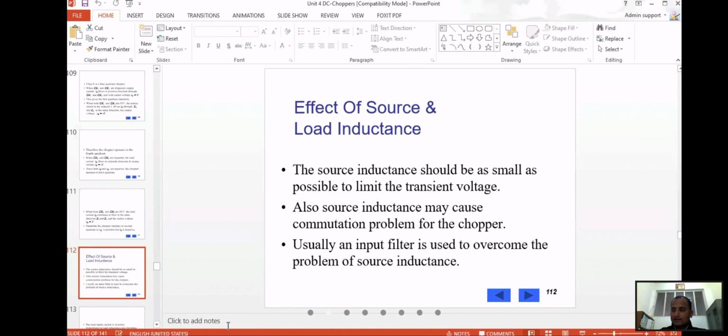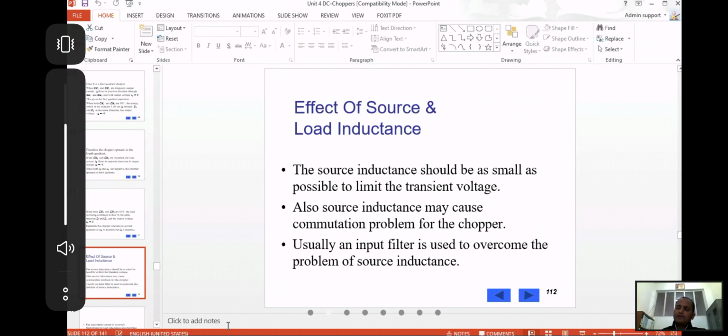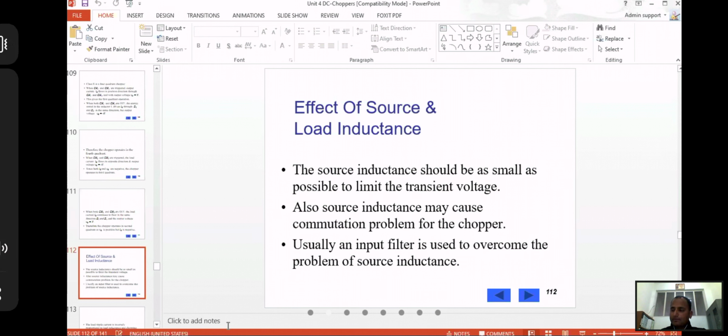It can charge when the circuit is conducting, and store the electrical energy so that the output voltage can be continuous. When the circuit is switched off, the chopper's output voltage, the load voltage, can be kept constant, because it discharges.